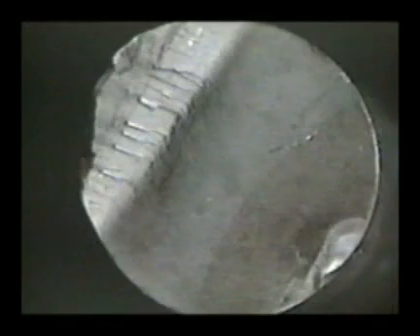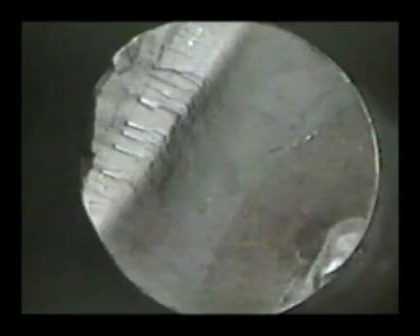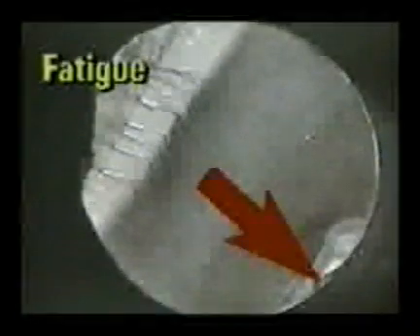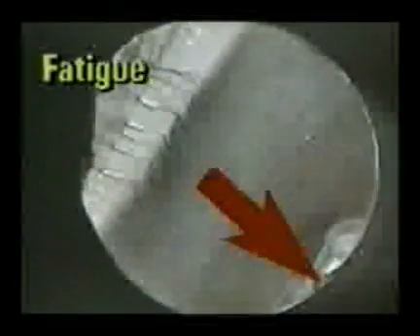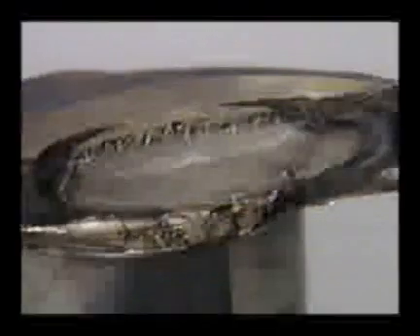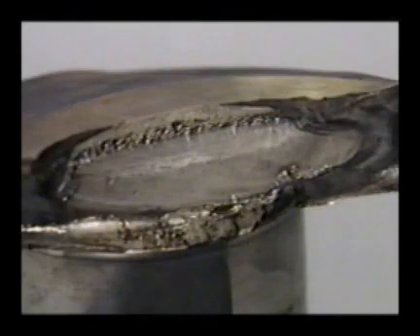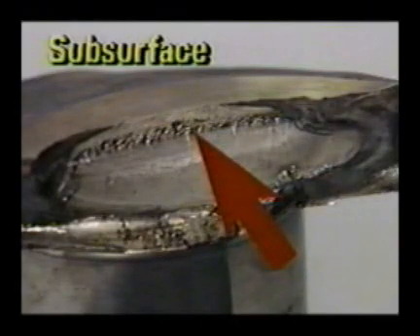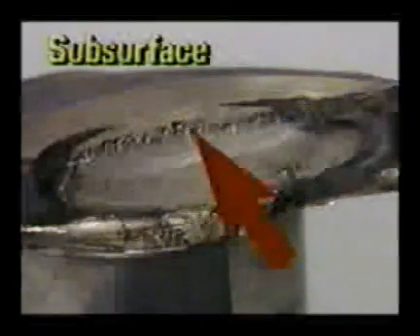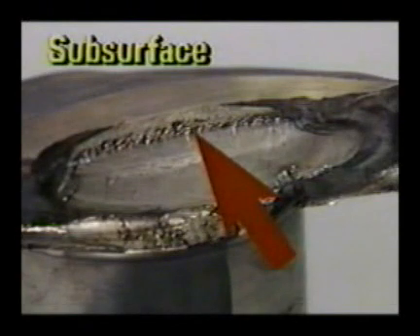Try identifying this fracture and tracing it to its starting point. The beach marks on this fatigue fracture indicate it started at the lower right with final fracture at upper left. Can you locate the initiation site on this fracture? Is it surface or subsurface? You should have noticed that ratchet marks and beach marks started inside the crankshaft. Therefore, the initiation site is subsurface.